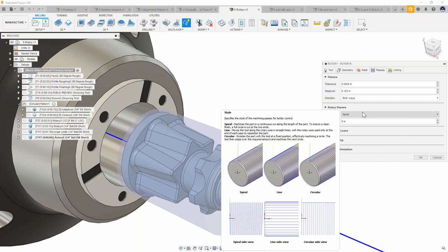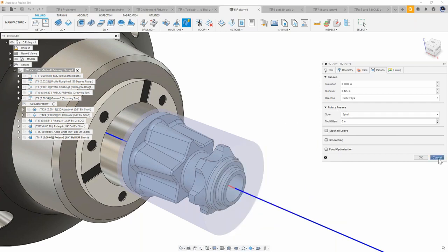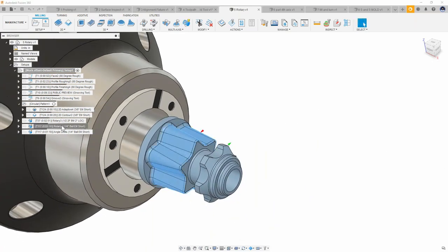So it is going to continuously spin that 4th axis so I could machine a part like this, because this would be a particularly tricky component to do multiple orientations on, and especially if it wasn't symmetrical. If it wasn't symmetrical, it would be even more difficult because I would have to make a tool orientation or something for each individual vector or position that I want to machine from. So let's take a look at some of these and how they work.